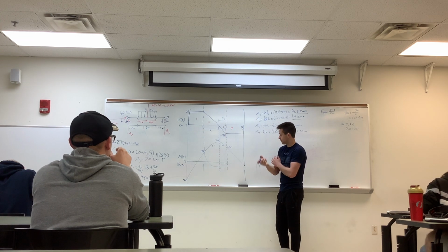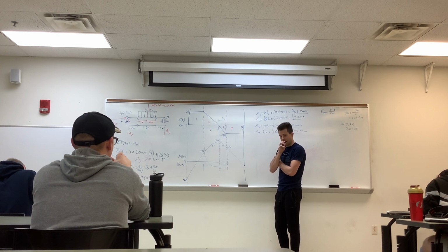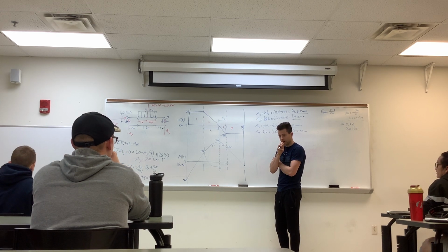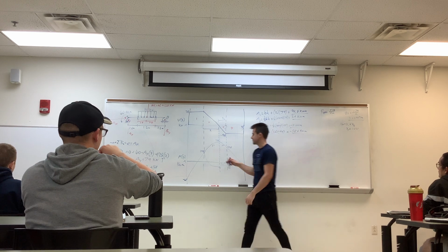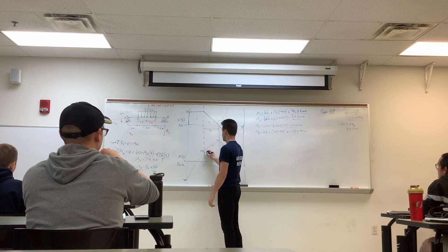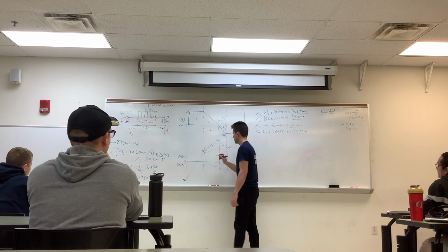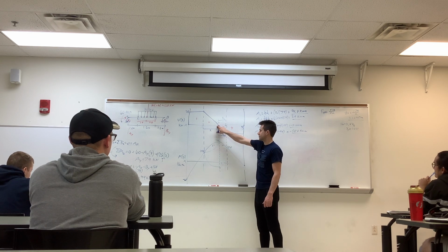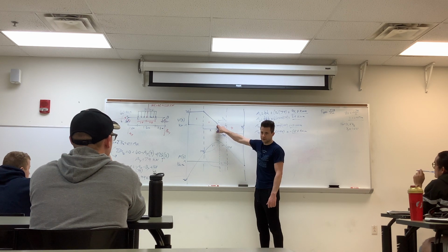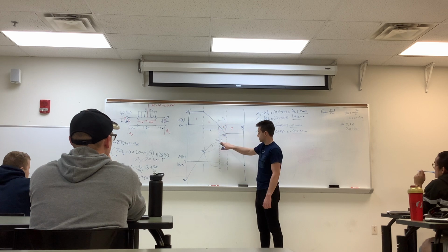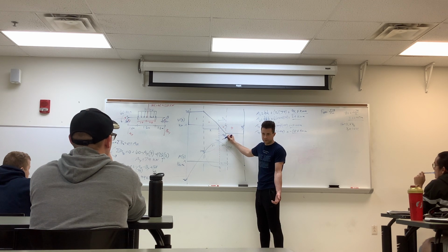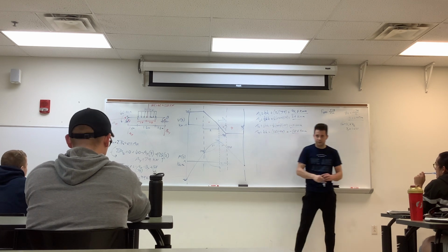So I know it's going to end up at that 73.8 or whatever. Why is it not, what is that? Because at the point at which it crosses the shear diagram, the slope of the moment is 0. So even if you do this, your slope here is not 0. Okay, that makes sense. Yeah.